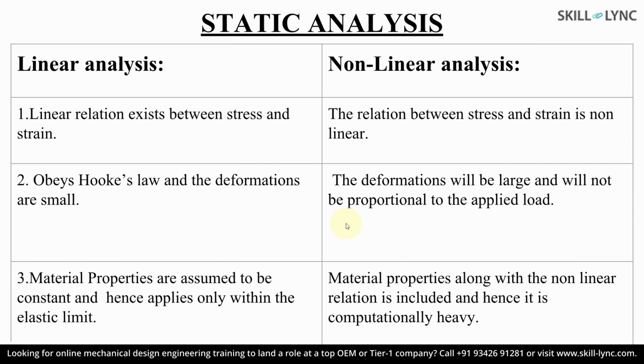Static analysis. As the name suggests, simulation is going to be independent of time. That is, the loads applied are not dependent upon time. dF by dt is going to be 0. Hence, we call it a static analysis, and this static analysis is broadly classified into linear and non-linear analysis. As the name suggests, there is a linear relation between the stress and strain in the linear analysis, while in the non-linear analysis, the relation is no longer linear. Secondly, in the linear analysis, the material obeys Hooke's law and the deformations are small. But in a non-linear analysis, the deformations are large and will not be proportional to the load applied.